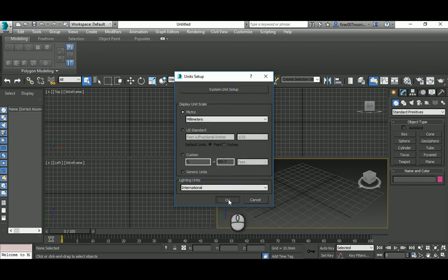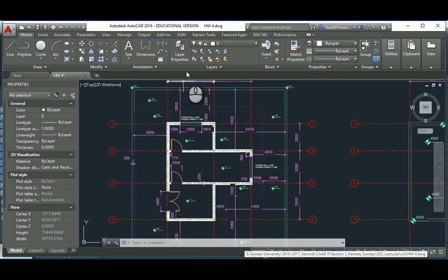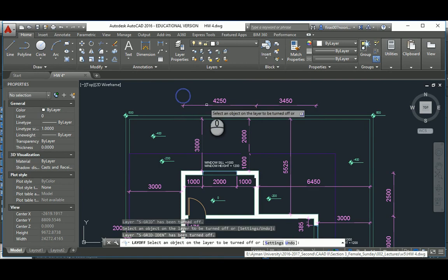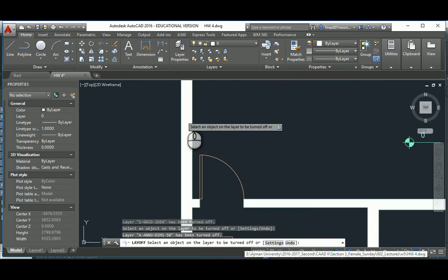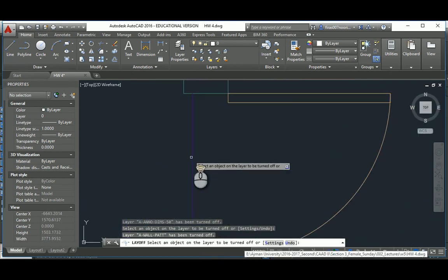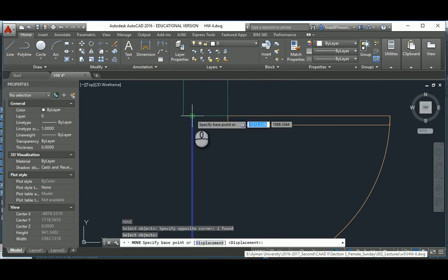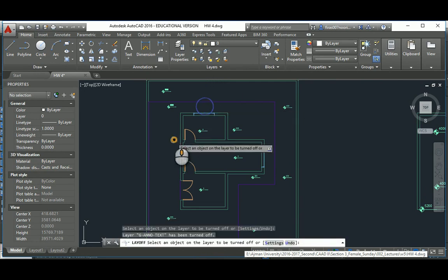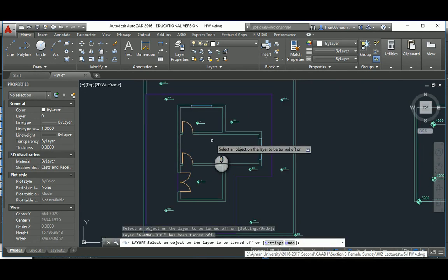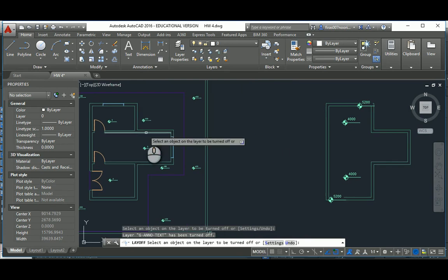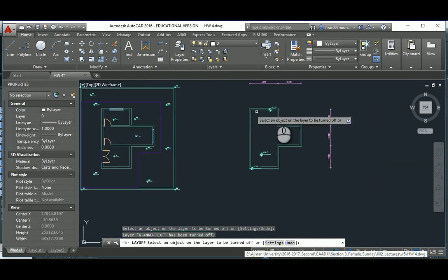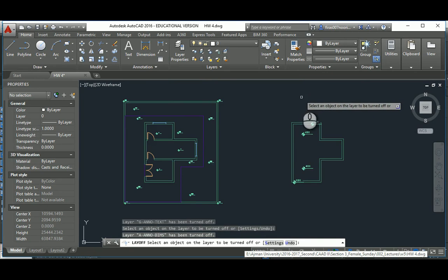So we're all good. Back to CAD, and now with the off layer command, turn off everything that you don't need, starting from the grid, bubbles, and the dimensions, and definitely the hatch. In this case, this line is in a scary place, so I'm just going to push it that way. Text probably here. Now that's my building, and as you can see, those are the exterior walls of it. I'm always going to start with the exterior walls, and the exterior walls go all the way from -200 to +5200. Turn this off also.